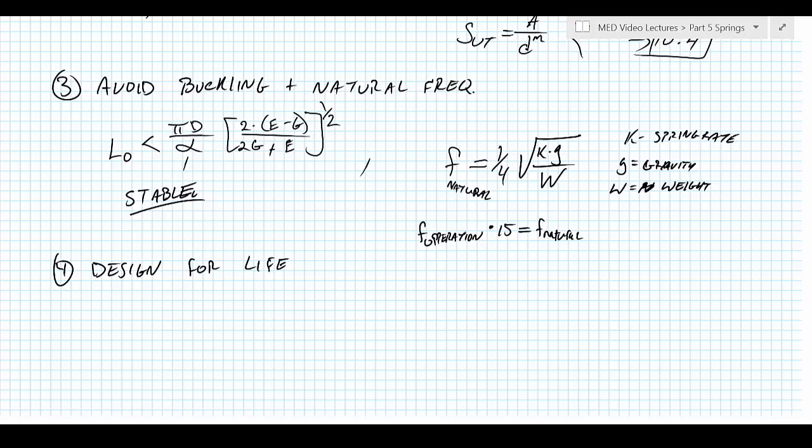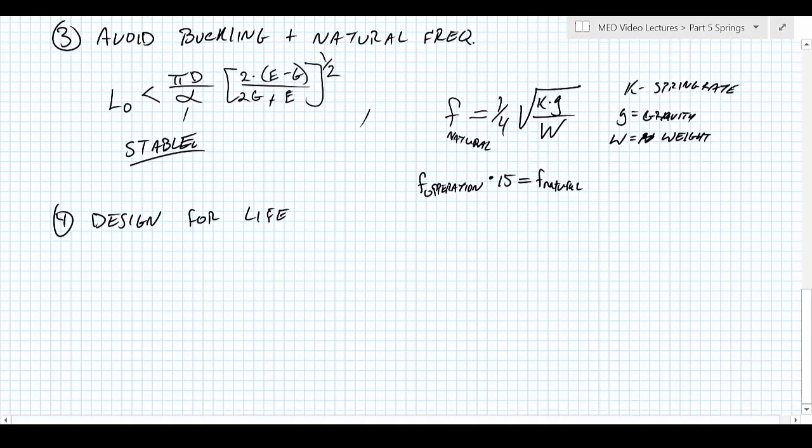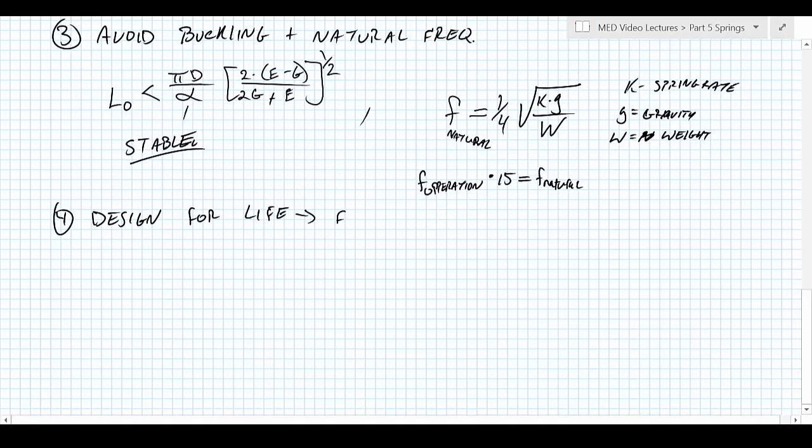So as we said, as we've checked in step 2, if we rule out yielding because we put the yield point after it goes solid, so after it goes solid, now we're talking more like it's the material itself, like a tube yielding, then the only thing now we have to worry about is fatigue failure. So here's where we get to apply those failure theories that we learned before.